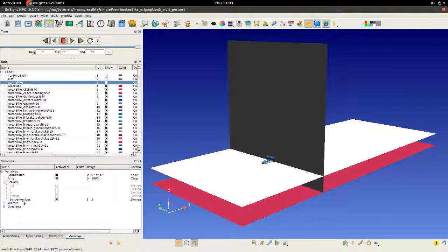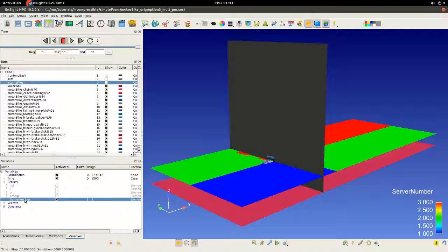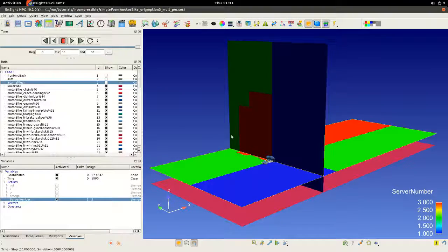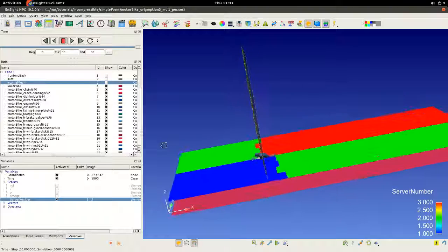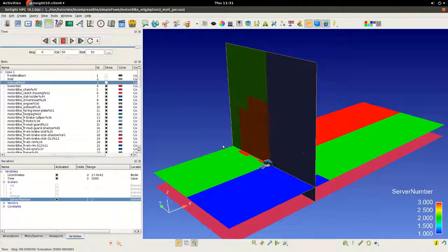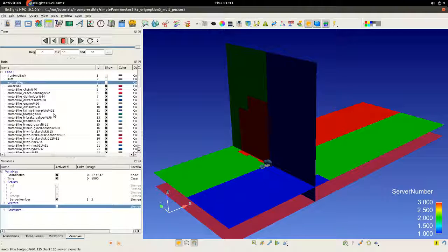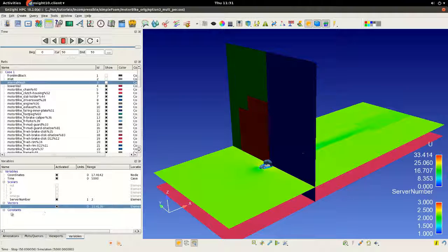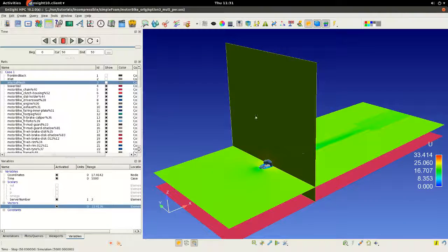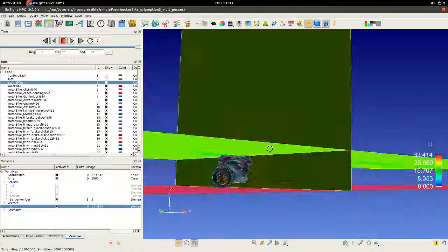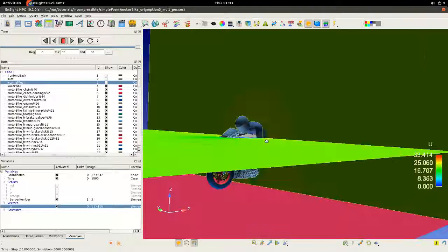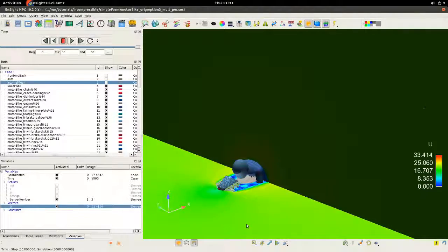Now we'll go back through and color this clip plane here and perhaps that clip plane there. So you can see the different server numbers. We have 3 different servers that are loading up the data, and we've essentially allocated 2 of the OpenFOAM processor partitions to each of the EnSight servers. Coloring and looking at things, for example, if I were to color here by velocity, we should see this is now a nice continuous velocity field that we could utilize just as we were loading a standard dataset, a single server dataset.